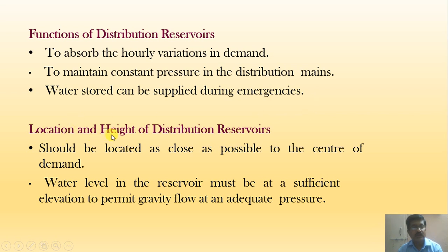Location and height of distribution reservoirs: it should be located as close as possible to the center of demand. Water level in the reservoir must be at a sufficient elevation to permit gravity flow at an adequate pressure.